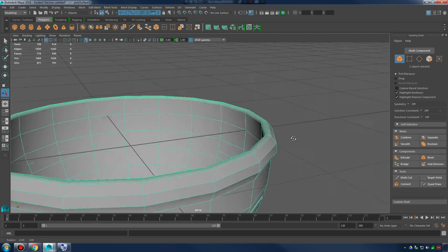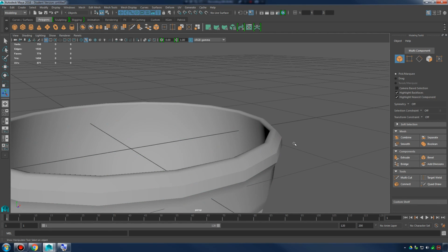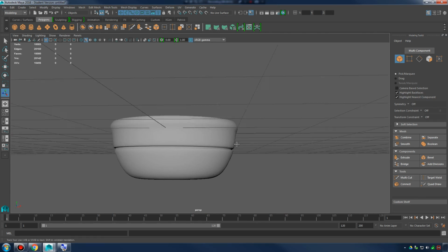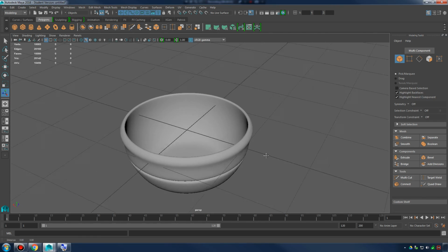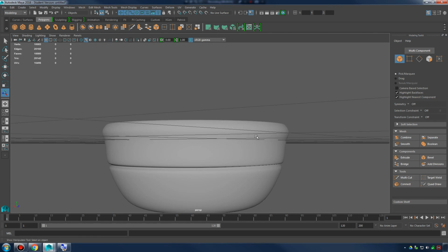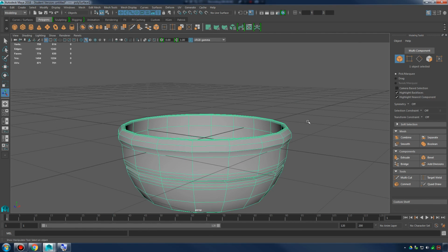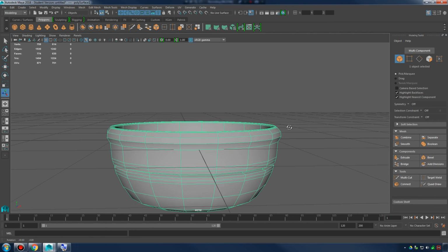That's what beveling can do for us. It helps us add these nice organic rounded off shapes. I press 3 on my keyboard to check out what's going on. Everything's looking so good so far. I don't see any errors in my topology. Alright, so we've hit Bevel Face. Now we're going to introduce Wedge Face, and this is pretty handy in certain situations.